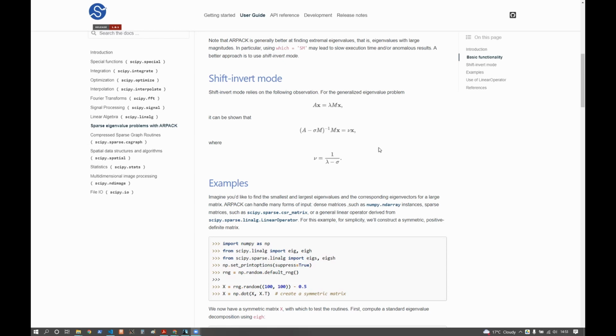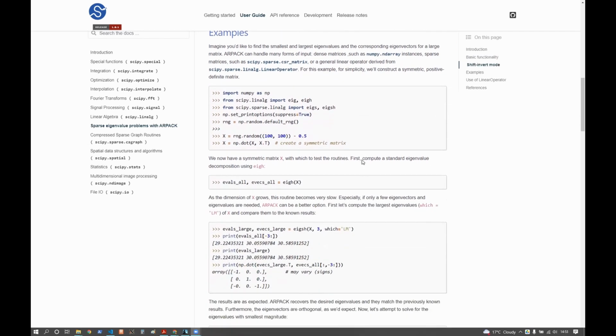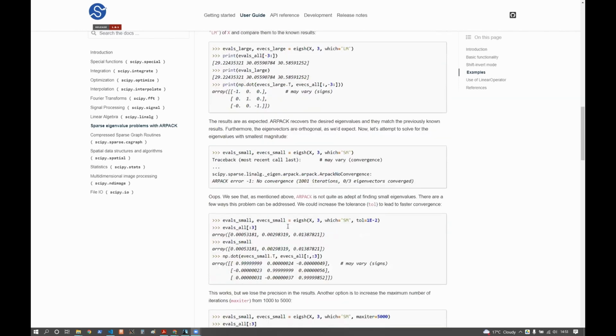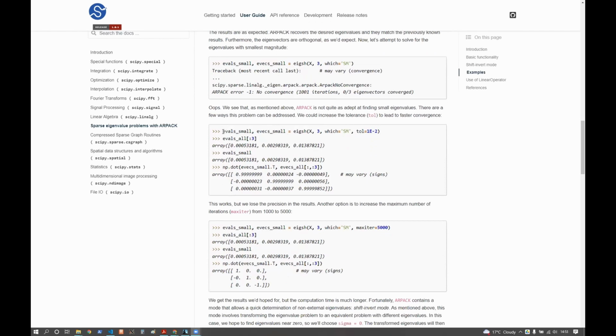So we're looking at any modes that are closest to 0 and above. And of course, it depends on how complex your problem is. But in our example, in a minute, we will only look at the first 10 modes or so. So this shows you how you can actually implement this eigenvalue solution problem with ARPACK. And it comes back to a very simple equation.